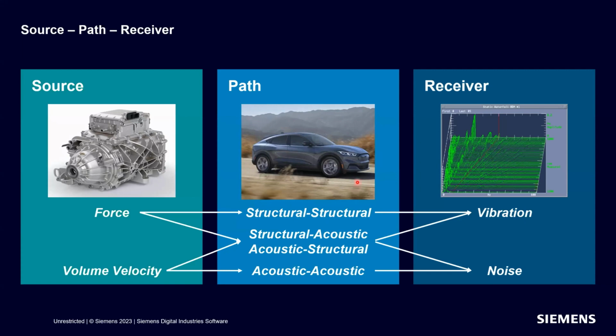It could be an FRF that we simulated for a new vehicle body, for example, and then we'd want to predict how the existing source will work in that vehicle body. So it can be used as a troubleshooting method on current production hardware, or even in advanced analysis, trying to predict what the levels are before you actually build the product.